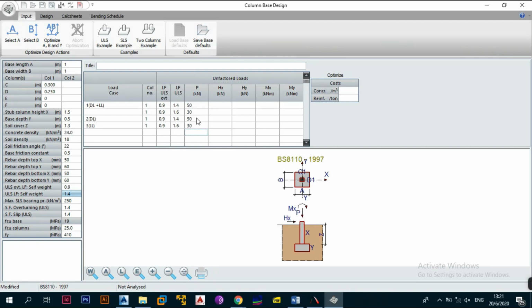So this is how you enter the loads. As you can see, you can put as many load cases as you want, and you can even combine many columns or rows under one load case. If you wanted, you could say insert. And in this case, maybe you want to divide even this one into 2. You could say C, then V, then this will be 1.4, also C and V. And this one you could change to 25 and then change this one to 25. It would still have the same effect, right? It's still loaded under the same load case, so it will apply.